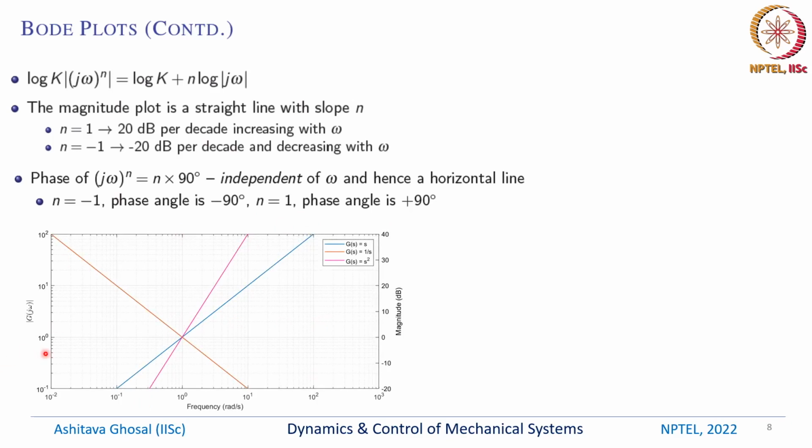So this is the plot of magnitude versus the frequency. What you can see here is that the x-axis, the frequency, is in the log scale. On the y-axis you have the magnitude, and MATLAB also tells you the magnitude in dB. So basically this is the magnitude, and this is 20 times that number. You can see here 10 to the power 1, so this is here 20. Magnitude in dB is 20 log of this.